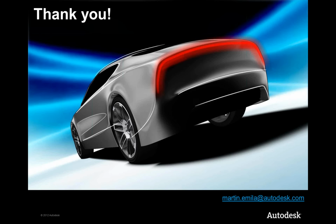Okay, we've got a question here about where the zebra shading is in Maya. Is it possible for you to demonstrate that? You need to do it. So it's not available by default, but there's a simple workflow. Create an environment ball and apply some kind of zebra texture on this, and use it in a shader color channel, and after this it looks like a zebra shader in Alias. So it's not available by default.